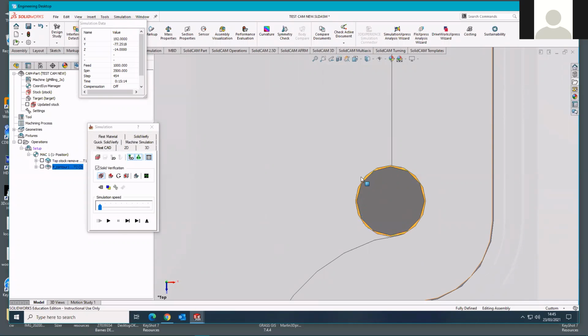It's not engaged in the work. And we can affect that depending on the cutting data that we can get from the tool manufacturer. There will be recommendations over how much step over, as it's known, the tool has, or how much tool engagement the tool will withstand without bending or possibly snapping.